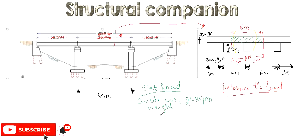Remember, this is 250 millimeter, so the area of this portion here I have to determine first. Area is equal to the thickness. This thickness here is how much? In meter, it is 0.25 meter. I have to multiply it by the total length here, which is the length of the beam resting on this beam, 6 meter.